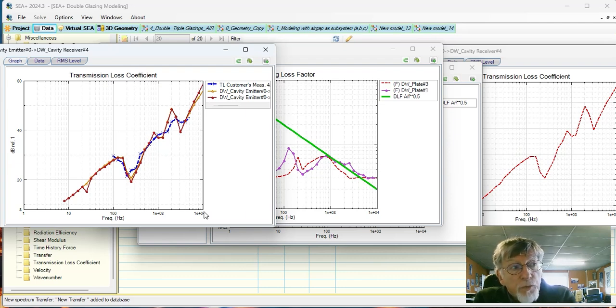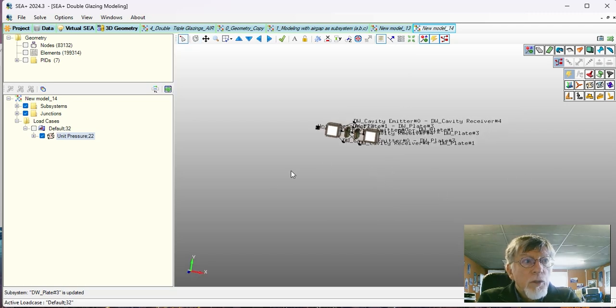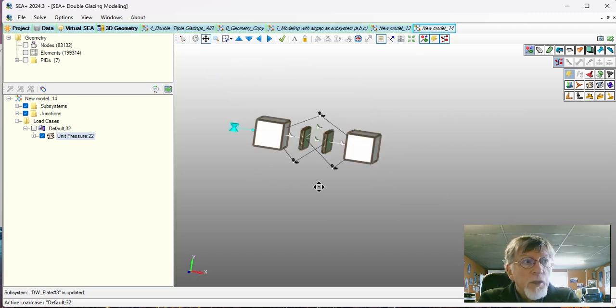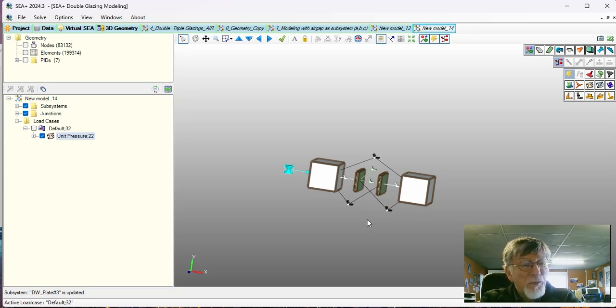And we know that if really we are keen to being on the safe side, we can just add some measurement of the panel damping, and only with this property plus some thinking about the coupling loss factor between the two plates, or even a measurement of it, we can really have a perfect model for transmission loss at a very low cost.